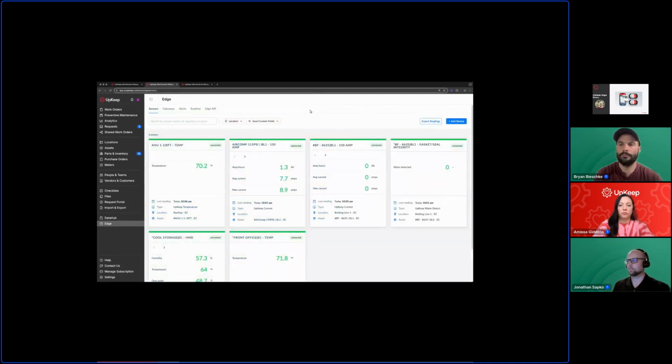When we talk about meters, they're different than sensors. Pretty much every CMMS that calls itself a real CMMS has a meter functionality, meaning you can set up consumption points to enter data into. That could be runtime hours, cycle counts, temperature, vibration, current, whatever metric the company we're talking about is trying to track.